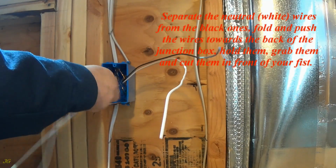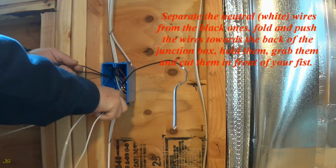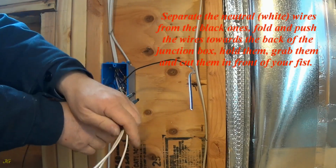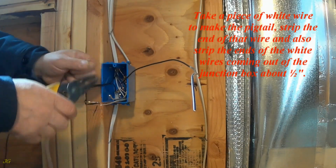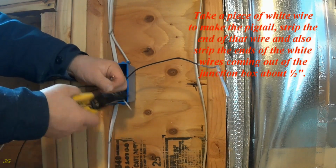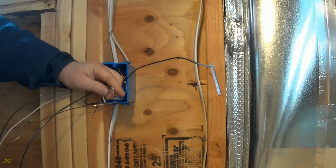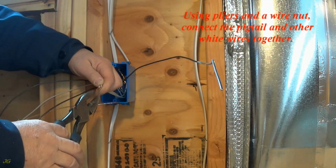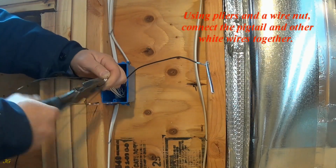Separate the neutral, white, wires from the black ones. Fold and push the wires towards the back of the junction box. Hold them. Grab them and cut them in front of your fist. Take a piece of white wire to make the pigtail. Strip the end of that wire and also strip the ends of the white wires coming out of the junction box about 1/2 inch. Using pliers and a wire nut, connect the pigtail and other white wires together.